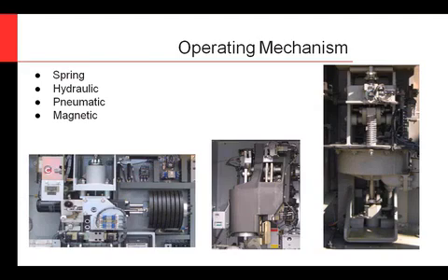So the reason they do this is you're never without the ability to trip. If there's one thing this circuit breaker needs to be able to do, it needs to trip on command. You need to be able to at least do a close immediately followed by an open to interrupt that fault in case you close in on a fault.